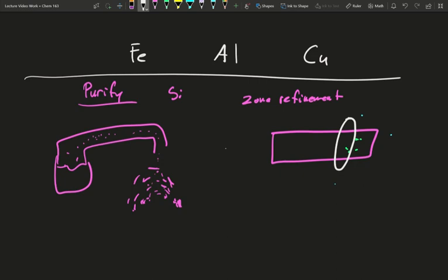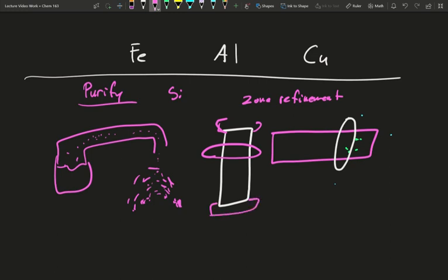Silicon, in fact, we just dangle it. You'll have a silicon rod. You'll have the ring. They're held on top by some clamps and on bottom. And the ring is narrow enough that the surface tension of the molten silicon is actually enough to keep it from flowing down this cylinder. So it will melt. There'll be a very thin line of melt, and that doesn't pop out. Just like water surface tension keeps stuff from overflowing, the silicon surface tension keeps it from overflowing.